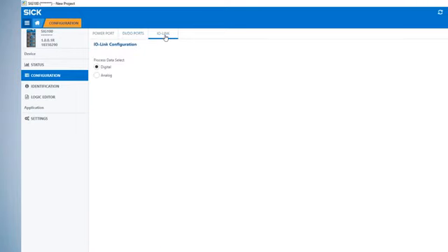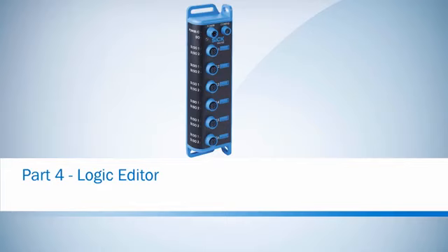The IO-Link page simply allows the user to toggle between digital and analog for the process data frame. As mentioned previously, digital allows an IO-Link master to send up to 16 discrete states to the SIG100. Analog allows the IO-Link master to transmit an integer value to the SIG100. Differences between the two can be observed by clicking the Pinout button in the upper right corner of the interface.